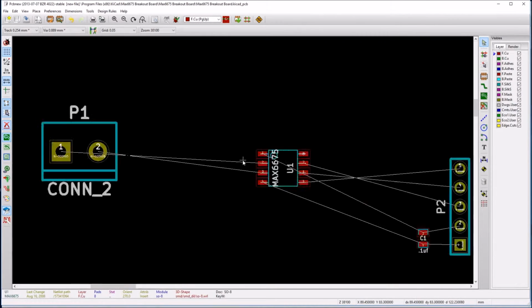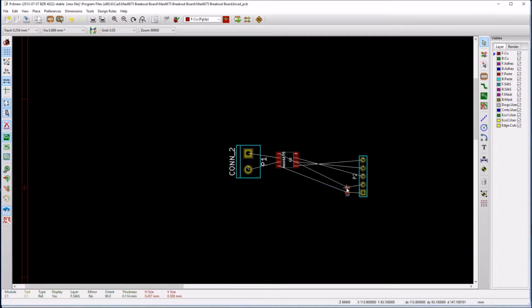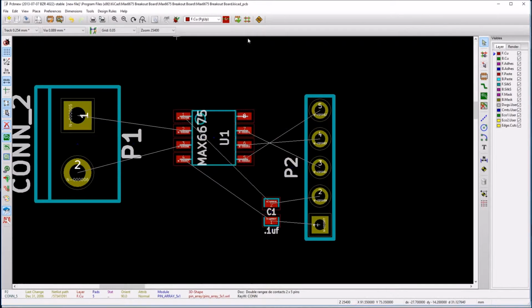So there's a couple things. It's pretty similar to how Eagle works. In this, it highlights the field when you have it, when you're putting down a layer or a track. It's a little bit more complicated in setting up the track thicknesses, but it's not really that much worse. It's pretty good, and you can change the track here obviously if you have more set up. One of the things is that this red one is the top layer, and this green one's the bottom.